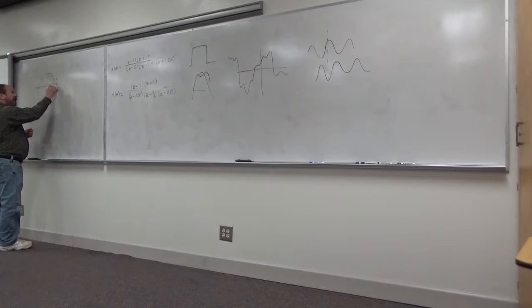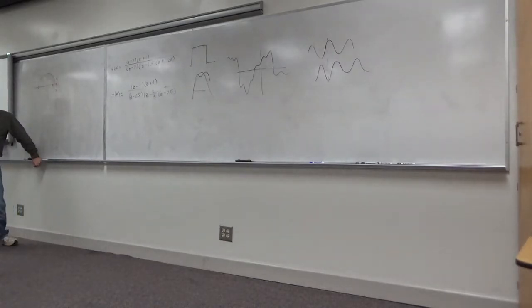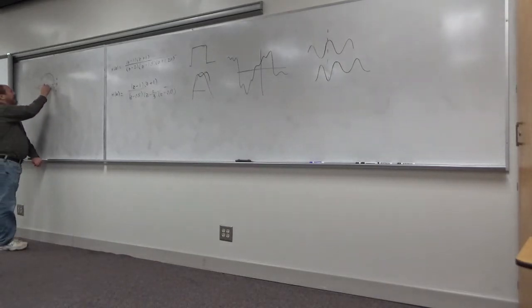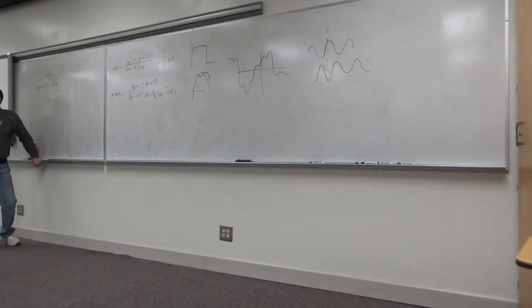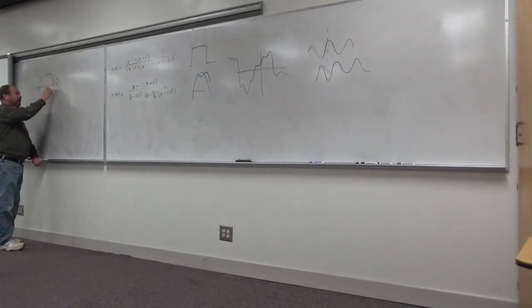What can I do? I can redo it, a different filter, and this one will have the same gain response. I'm going to reflect that one in there by taking its reciprocal. And here's something I want you to appreciate, but it really doesn't matter in the end. When I take, let's see, that one's out there and that one's out there. When I take the reciprocal of those, they'll go inside the unit circle, won't they? But this one has a positive phase. That one will actually go down here.